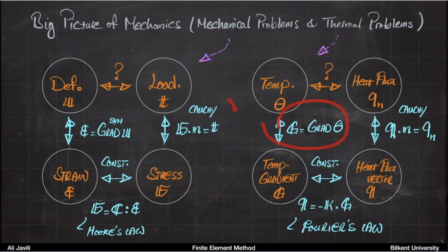So this is a vector. This is a matrix or second order tensor. So basically your mechanical problem is one dimension higher in its own space. So here again, stress is a second order tensor or a matrix. So stress is a matrix, strain is a matrix, and this thing has 81 components. Whereas here, this is a vector, this is a vector, and K, conduction, has 9 components.